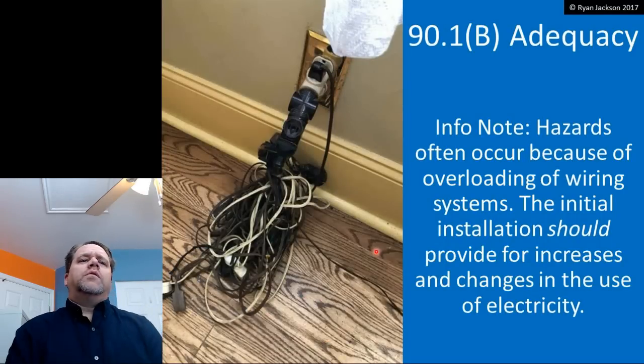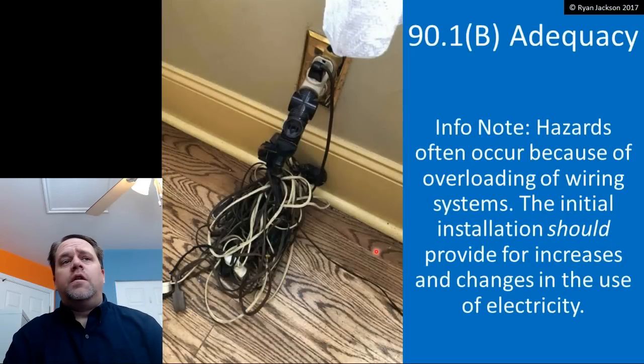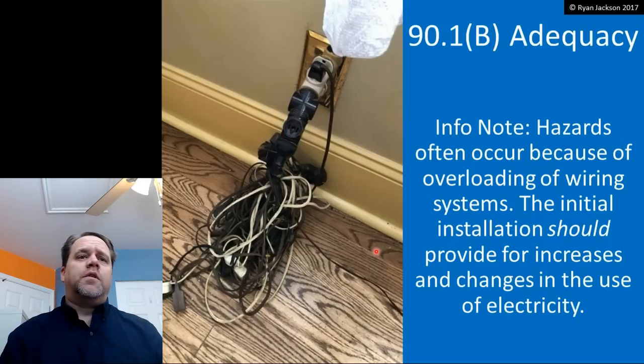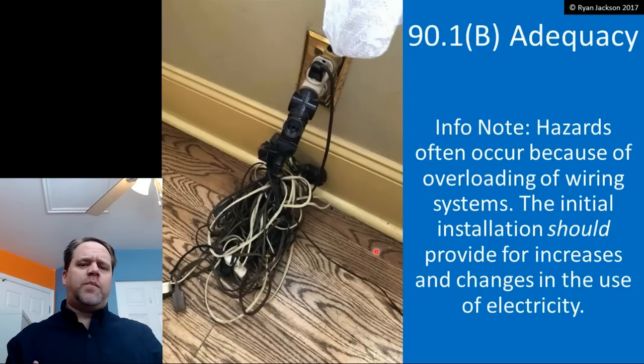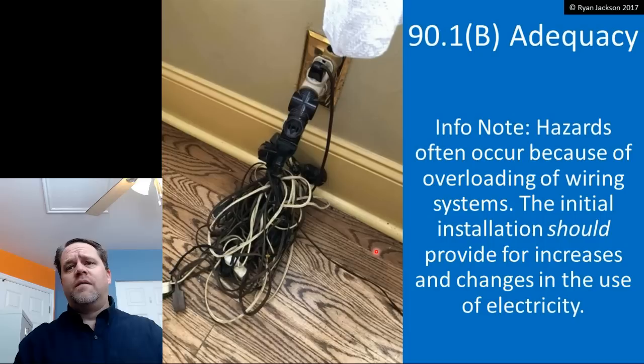There's an informational note that says hazards often occur because of overloading of wiring systems. So the initial installation should provide for increases and changes in the use of electricity. So as we can see in the photograph here, that's going to be an obvious hazard, and that's something that we should try to avoid by planning for future expansion and future use of electricity. It's an informational note, and that means it's really not part of the code. It's not an enforceable requirement, but it is good information. You should do your best to plan for the future.